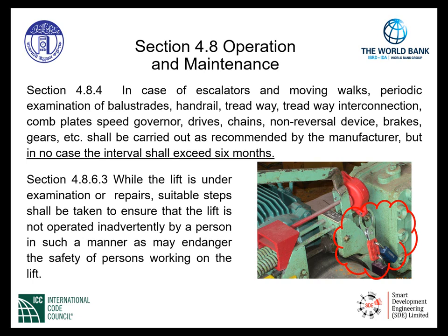The photo on the right-hand side indicates what we call lockout tagout. This is a method of locking out the control or disconnecting means for electrical motors and electrical equipment, where we actually lock out and tag out by means of the information on the lock who is working on the system. It provides safety to the people that are working on the equipment.